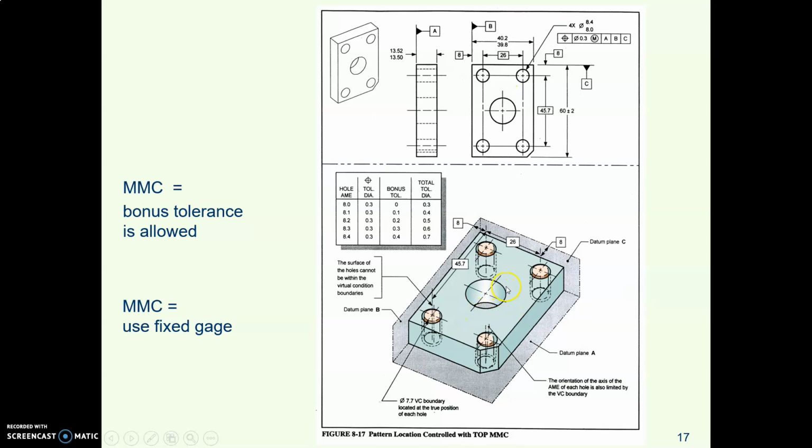But once they've figured out what size to make those pins, they don't have to measure everything under the sun. They just drop the part over the fixed size pins. If it goes on, it's a good part. Saves a huge amount of time.